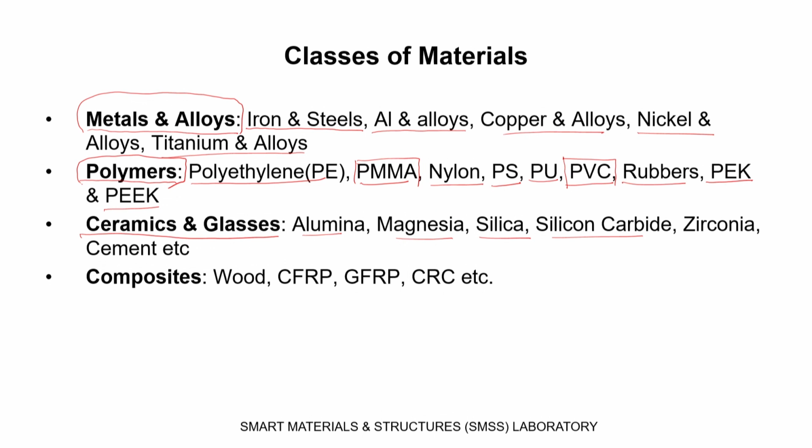Also, you can utilize this material for tooling purposes. Now, the best thing that they have is a very high compressive strength. So, wherever the load is predominantly compressive in nature, you can safely utilize them. The other good property that they have is good abrasion resistance, and also chemical corrosion resistance and temperature resistance. So, for this type of application also, ceramics and glasses are very good materials.